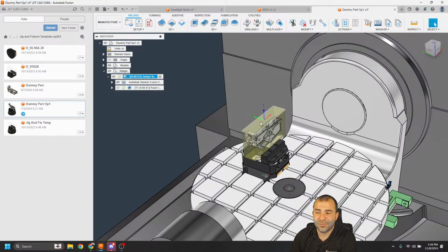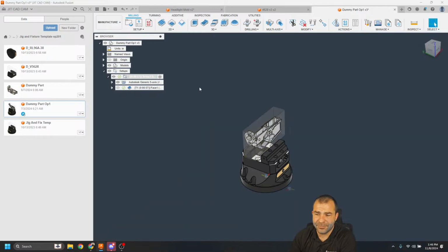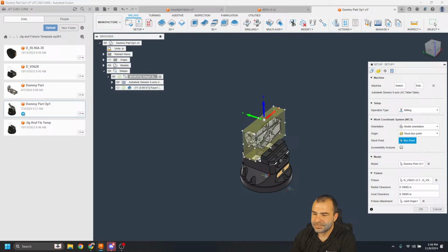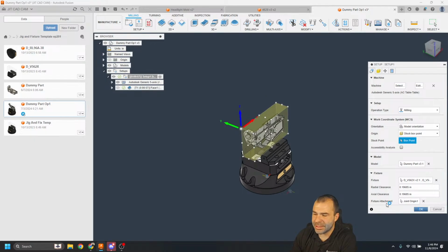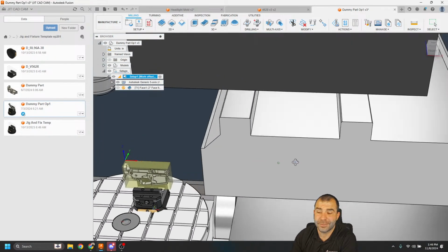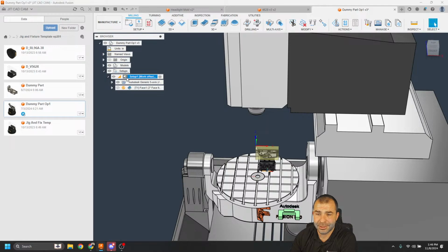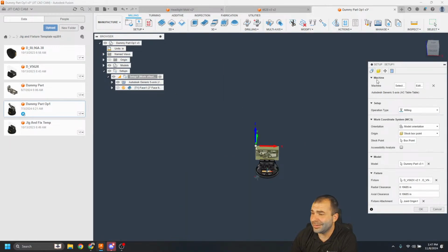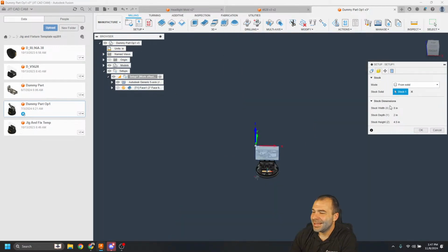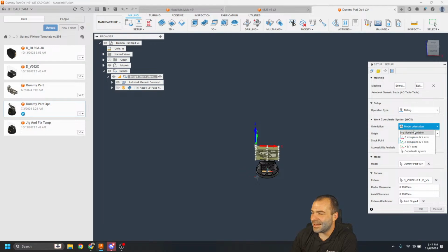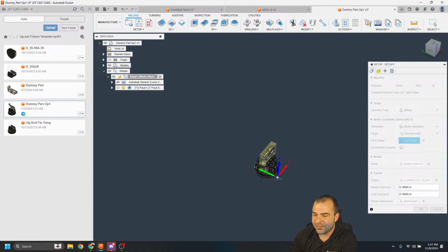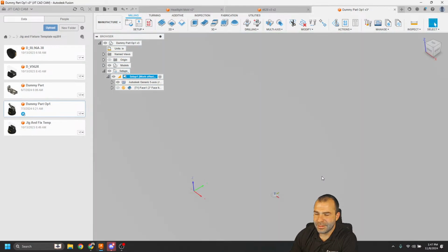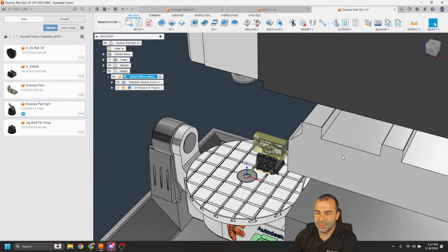And then the distance from your work offset, which we would have to move also, because we would go off that same point that we used for our joint. Actually, our work offset would be that joint origin. I apologize. This is why I'm making a video about it on Wednesday. We would define that as a selected location also, because that is going to be our reference at our machine controller, right? So all of our machine moves, travels, tilts, and everything.